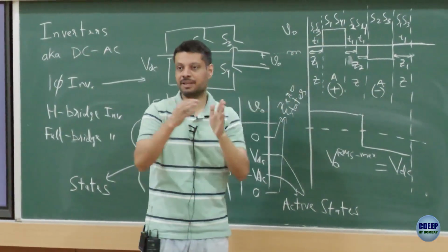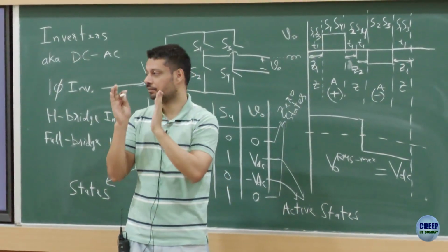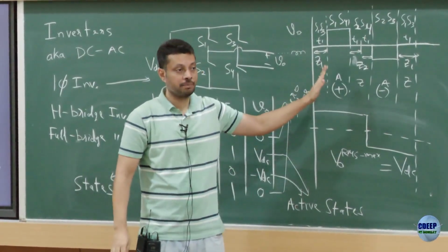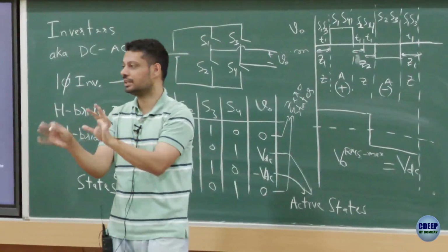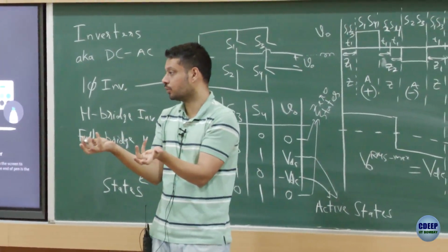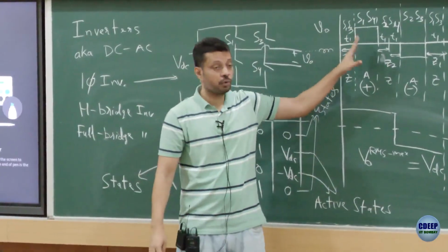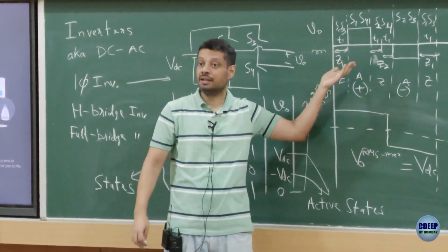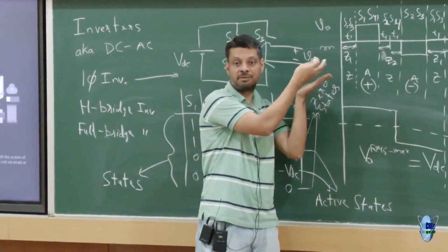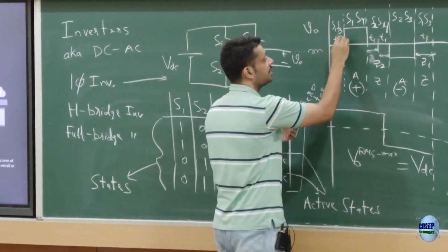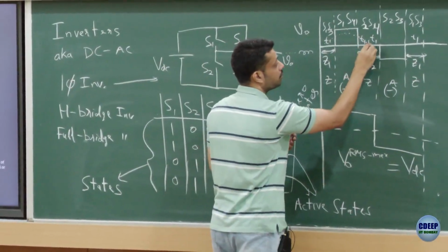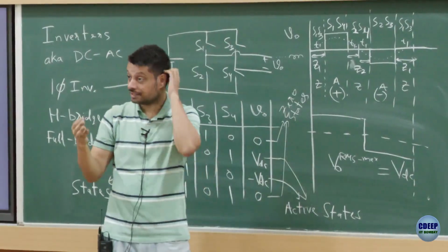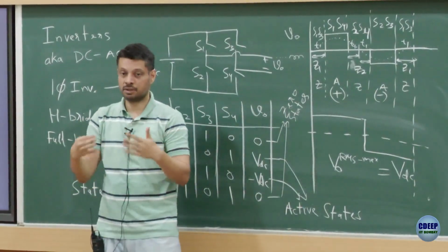This has multiple frequencies. If you just take the fan example again, you are only utilizing the fundamental component because other harmonics are creating these oscillations, vibrations. They are of no use. The main component which is being used is the fundamental sinusoidal, which is there. You cannot see it, but you can visualize it like this. So the fundamental RMS would matter more than the total RMS, and we will eventually see that.